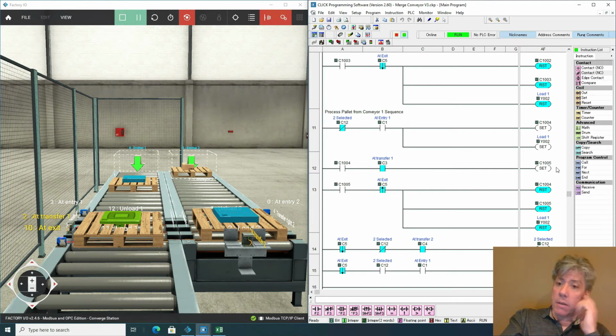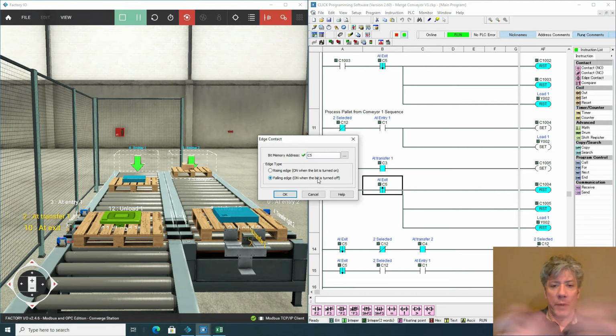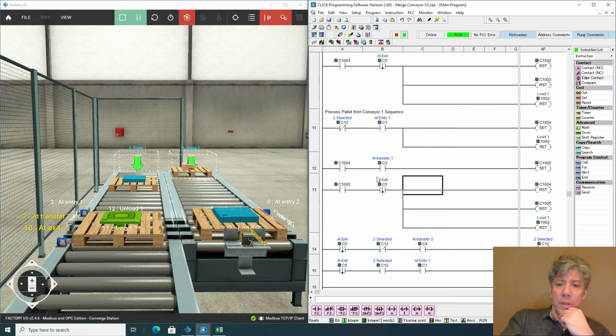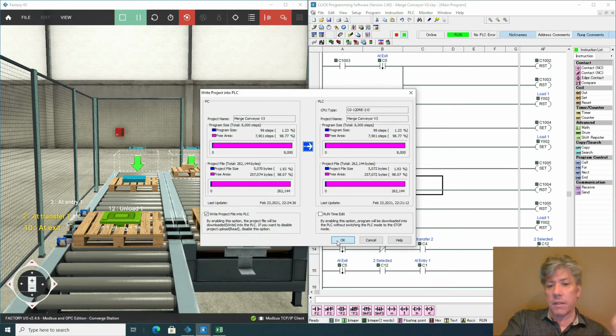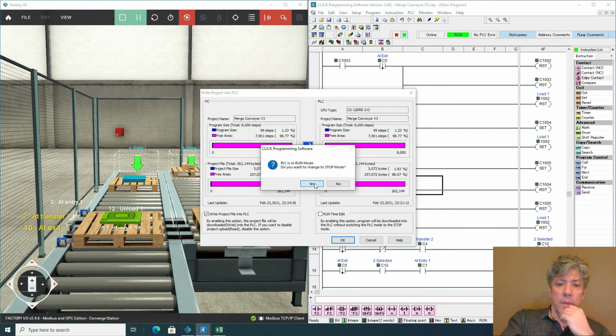Well, we somehow got to this point. Oh, because I've got a rising edge instead of a falling edge. Of course, I think I said falling edge, and I must have said rising edge. This is kind of like the scary movie, right, where the person's not watching what's going on, and you're screaming at the screen saying, "Hey, you said this, and you meant to do this, and you messed up." And probably most of you have been looking at this wondering why I said I wanted to see the falling edge, and I put in the rising edge. So sure enough, it saw the rising edge. The pallet hit that sensor and shut off the conveyor.